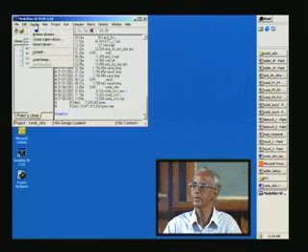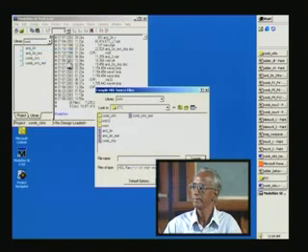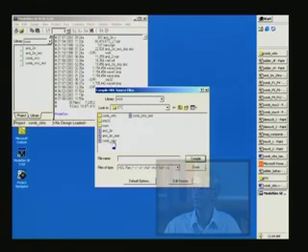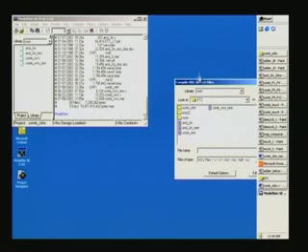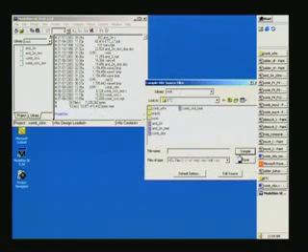Now let us compile the design, then compile. Then you see here combinational_circuits_test. Since we have included the design, there is no need for you to mention all the lower modules specifically. It is enough if you just compile the test bench. Double click here, and it will automatically start the compilation, which you can see in this window. I'll just double click on this file.